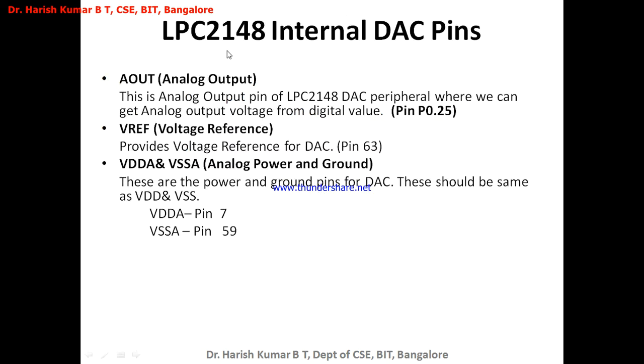Now the LPC2148 internal DAC pins. AOUT, as already told, is analog out. This is the analog out pin of the LPC2148 DAC peripheral, where we can get the analog output voltage from the digital value.